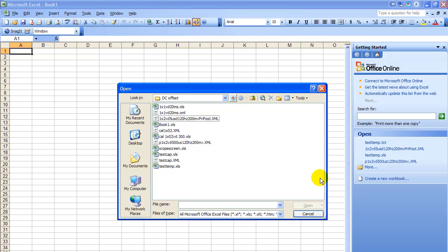is after the trigger. But we'll assume for a moment that we did a priority equal, which means the trigger's in the center of the data buffer. It's too hard to recreate this exact situation, so I'm just going to use the post file, and we'll assume that the trigger point is 1800 samples in, and we'll assume that we want to look at something that's 1200 samples in. That part of the waveform is what we want to examine closely.